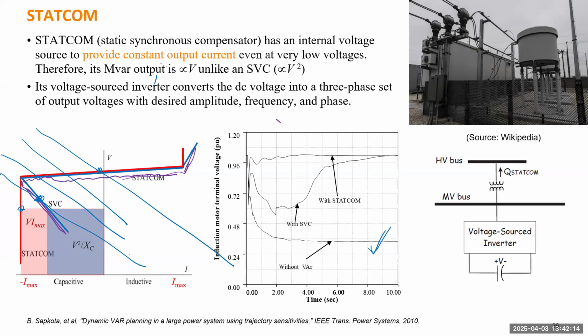In the load modeling, we mentioned if the induction motor stalled, do you remember how we should model an induction motor if we don't want to put in differential equations? If it's at normal voltage, the induction motor behaves like constant power or constant current load.